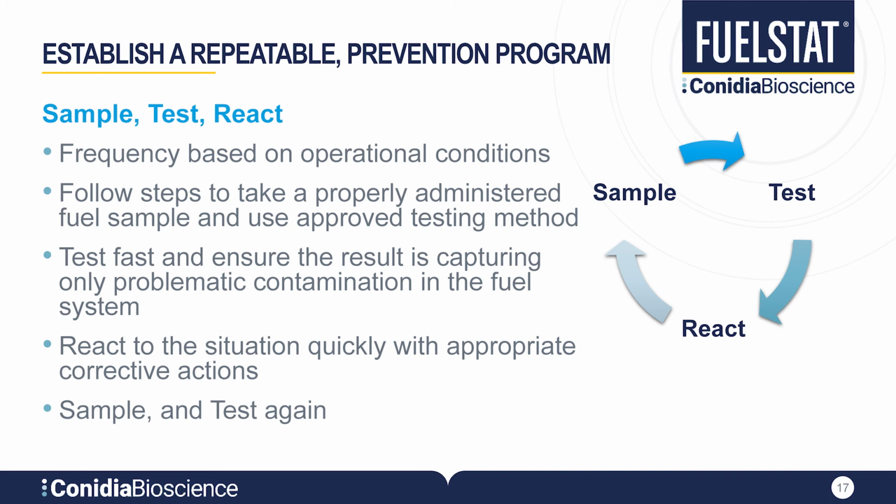However, any process should consider the PEST elements of preparation, environment, sample, and transport to ensure that the fuel sample is the best that it can be, helping to maximize the chances of obtaining the most representative result from any testing process. Speed of testing is vital, but the most important factor is the removal of as much water as possible from the fuel system to minimize both the risk of microbiological contamination and the cost of fixing the problem.